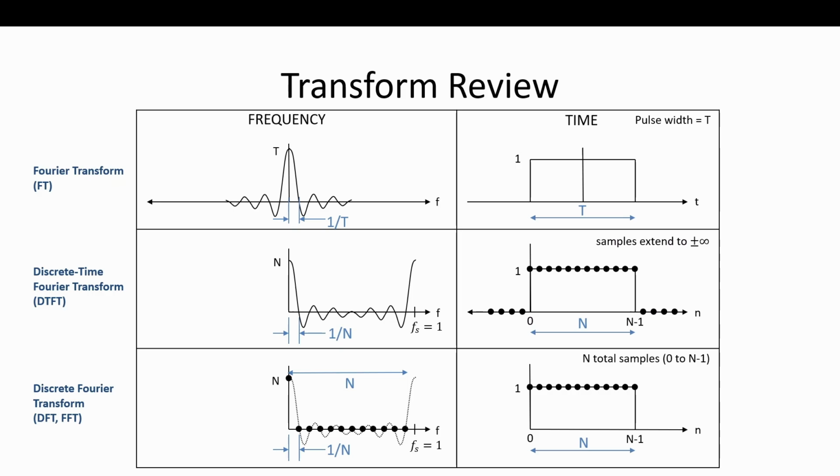That's what makes it the discrete time Fourier transform. The discrete time Fourier transform will be continuous in frequency. So when we get back to the filters and we talk about the frequency response of the filter, where we're just saying, hey, it's a low pass, when you look at frequency responses, whether it's a digital or analog filter, they're continuous in frequency, right?